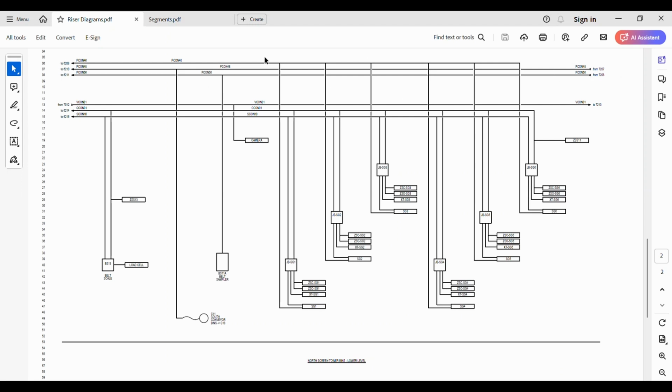conduits that are used for power. In this case, it's probably 480, but I don't really know. We are using conduits here for controls, for control cables. We have conduits here for signal cables. Each one of them is run separately. They all drop down into the same junction box, and then the appropriate flex conduit comes out to the devices, or these could be cord connections.